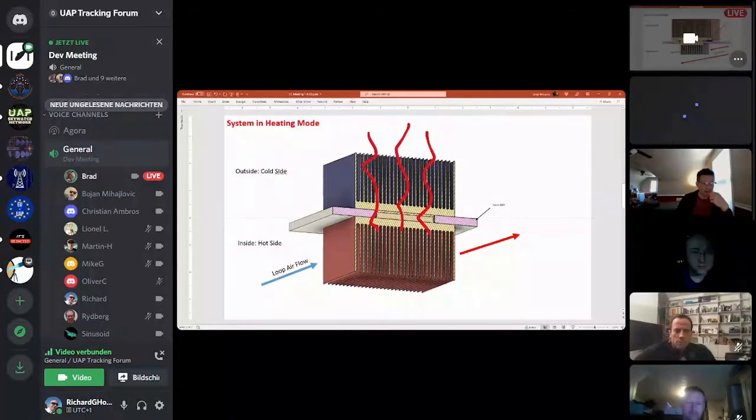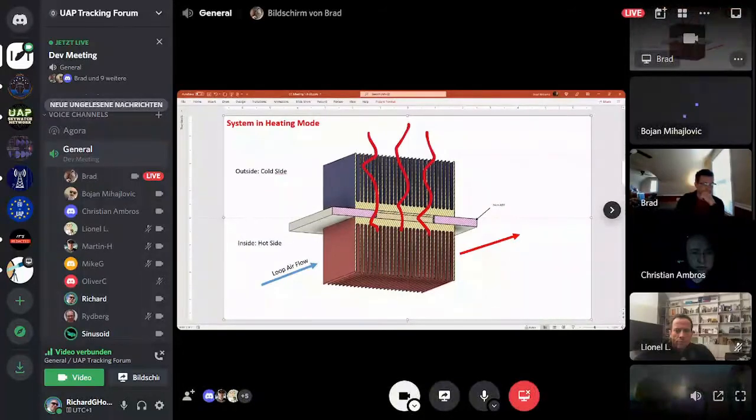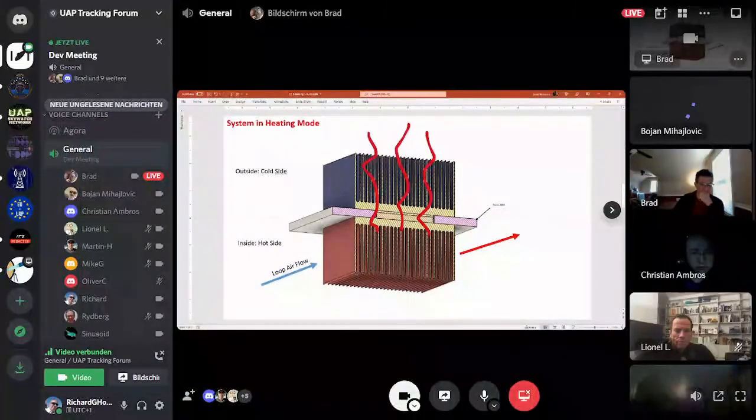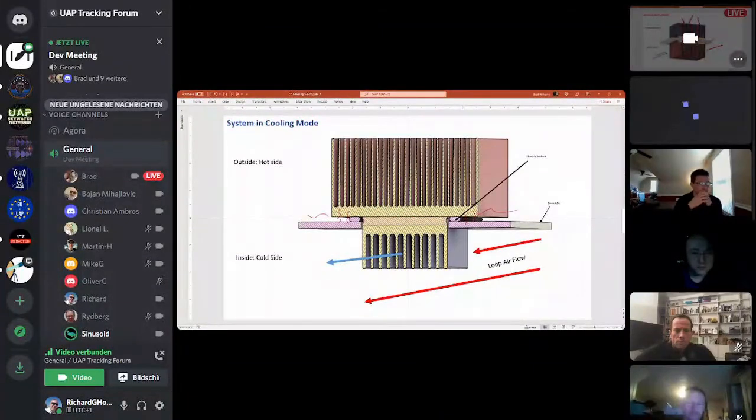And I think our focus needs to be on, like George said, trying to maximize delta T for cooling applications. Whatever tricks we have to do that, I think we've got to focus on that. Yeah, true. That's kind of why I brought up having a fan directly on the heatsink inside of the closed loop portion, in order to extract as much thermal energy as possible. That would maximize the amount that you're able to take out of the system.